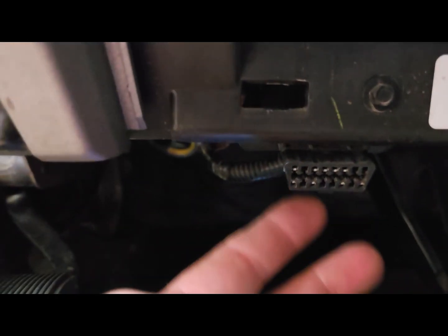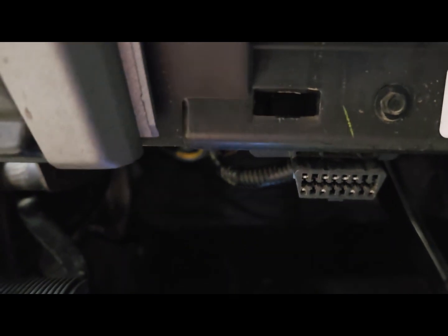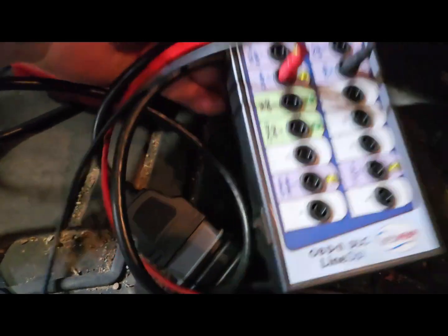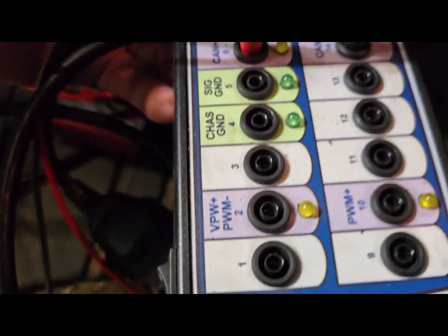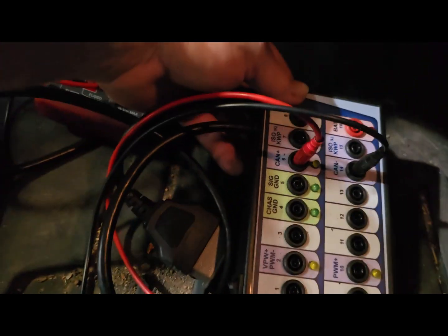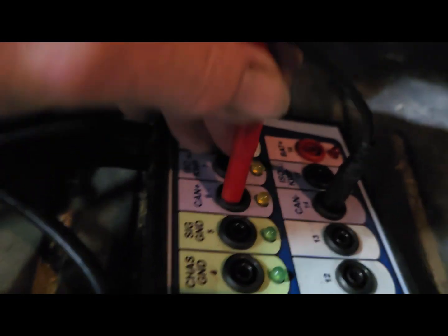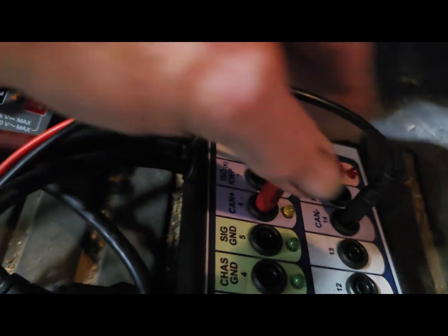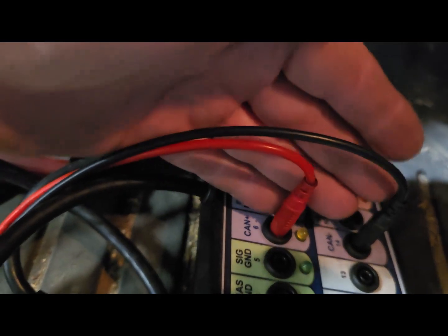Now, you don't want to stick leads inside this because then you're going to have terminal connection issues. So what you want is a breakout box. A good breakout box, this is the one that I recommend, something similar to this, is from AES Wave. What I like about this is that your leads plug in, and there's no wiggle. As long as your leads are good, then your reading is going to be good.